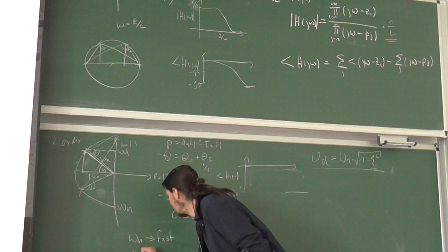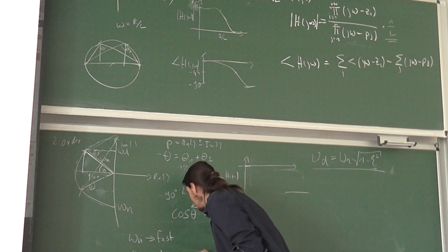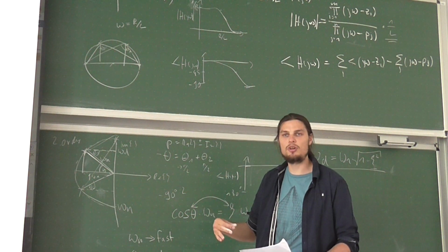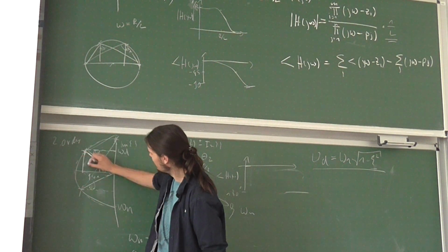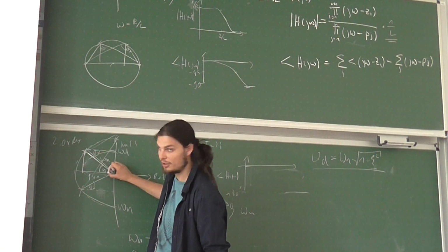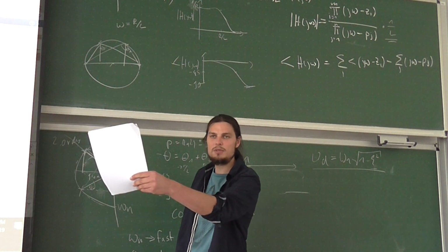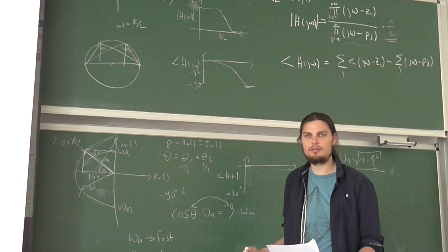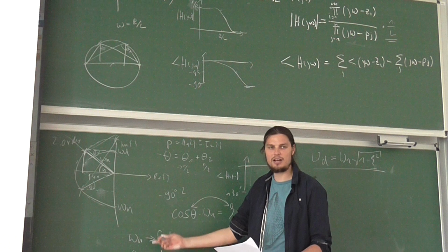And the angle tells us about damping. So the lower the angle, the more damped the system becomes, right? So if this was lower, it would be also slower, but also better damped. But if you keep this angle, you can increase the speed, and still the same damping is involved. Right? So these are basically the information you can get out of these poles.